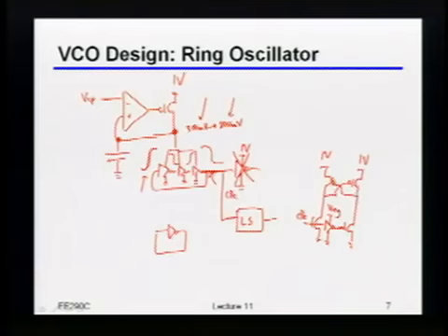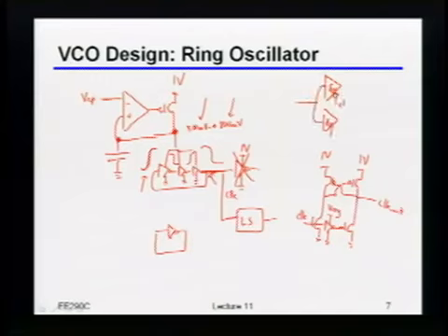Okay, and then as an example, let's say I take this clock out. Now I was hoping somebody would mention this particular one, because it turns out this one has some very particular nastiness associated with it. Remember, I'm using this clock for a high-speed link. We talked a while ago about it, but we'll talk about it more very soon. A pretty typical way for me to do clock recovery is to 2x oversample.